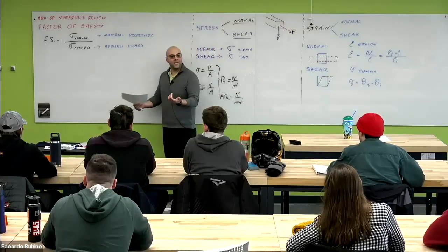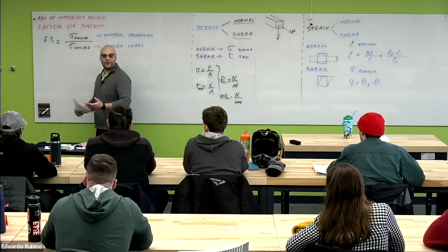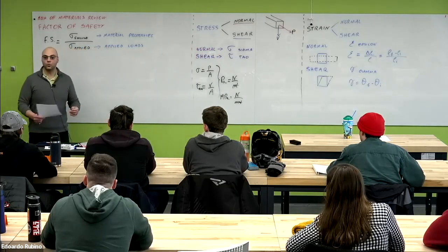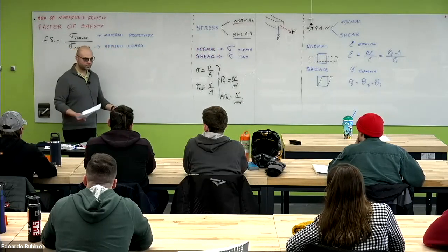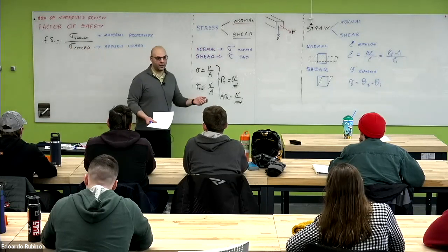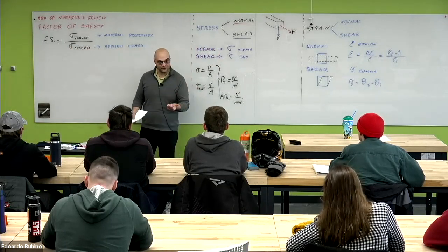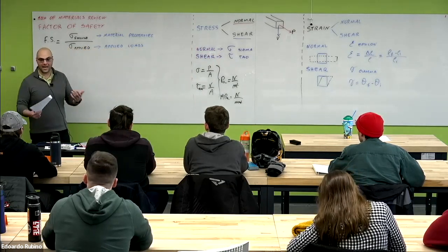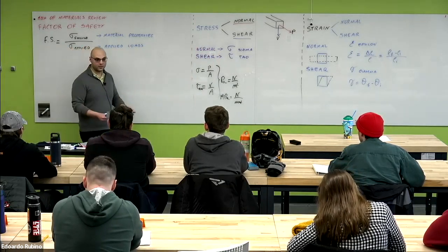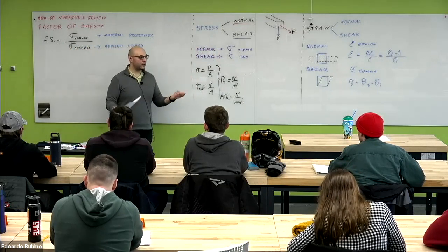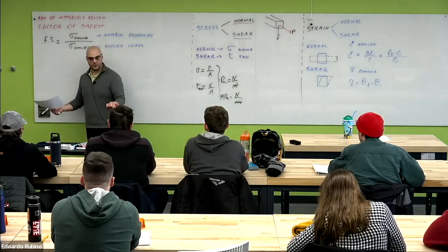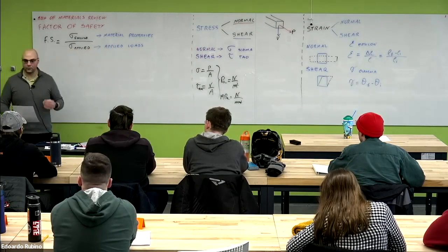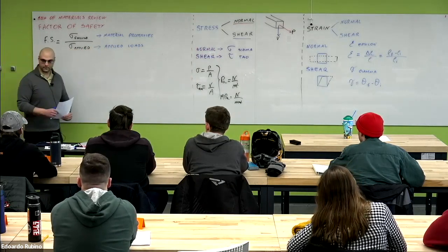If we look at a building or a bridge, the factor of safety can be higher, like 2, 3, and something like that. Of course, if we have a smaller factor of safety, on the other hand, we have to go through a lot more tests for that specific structure in order to make sure that it can withstand the loads that we are planning to apply on it. Make sense?